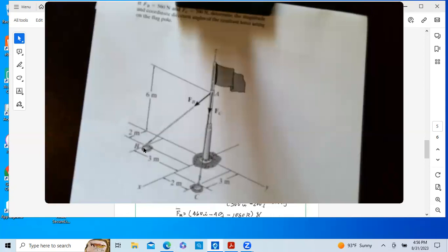The dimensions. It looks like it's this dimension out here. You have to orient yourself to the way the three dimensions are shown on the diagram. The rule is if you have dimension lines, they'll be parallel to the axis. So these dimension lines are parallel to the x-axis.